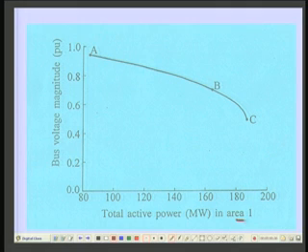Now, we can see here as the load in area 1 increases, the voltage at bus number 530 decreases, and at this point C you will find that beyond this point if you want to increase the load, the load flow will not converge, and therefore we have generated in this example the VP curve for a 39 bus system considering a particular area and a particular bus.